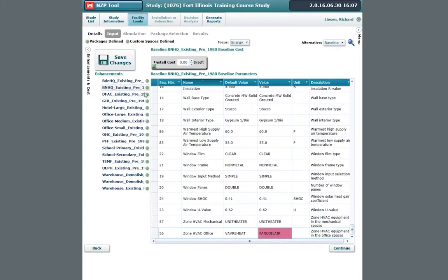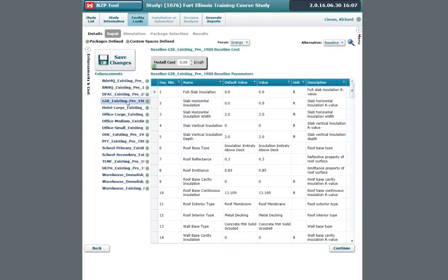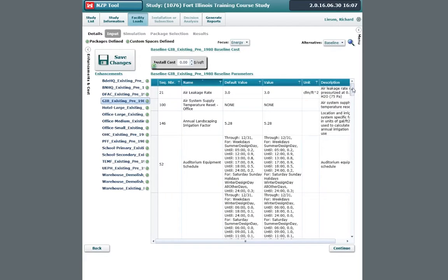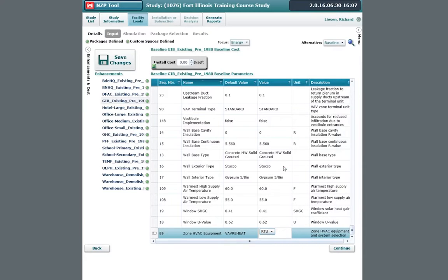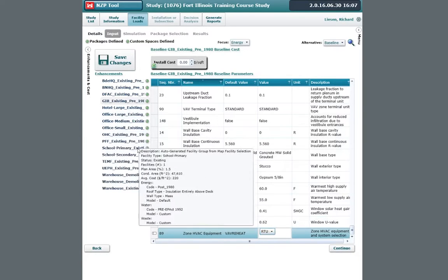It won't crash like some of those. If you change to the VAV multi-zones, and you don't change the terminal units to match, it will, because fan coil is a different system there. Okay, so I'm taking some of these pre-1980s and moving them to things that would be more in line with maybe that era, and trying to do something that won't bomb it right away.